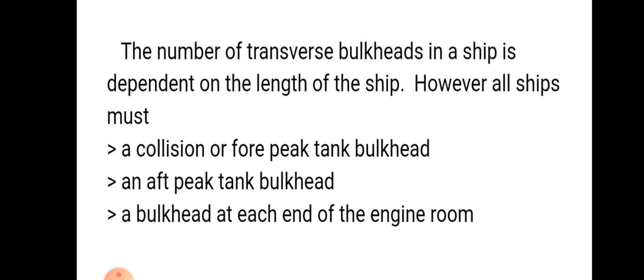The number of transverse bulkheads used in a ship depends upon the length of the ship. However, all ships must contain a collision or forepeak tank bulkhead, and an after-peak tank bulkhead at each end of the engine room. Okay.